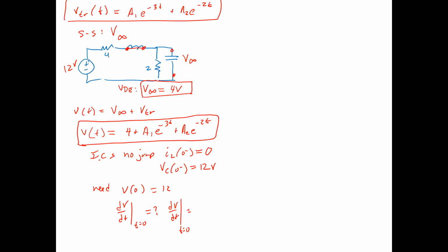We've done this over and over again, right? IC of 0, and then over C, right? Yeah, IC of 0 over C. So we just have to find what IC of 0 plus is, right? And this is the tricky thing. So in this case, we'll redraw the circuit where the inductor and the capacitor are at their initial values from t equals 0 minus, basically.